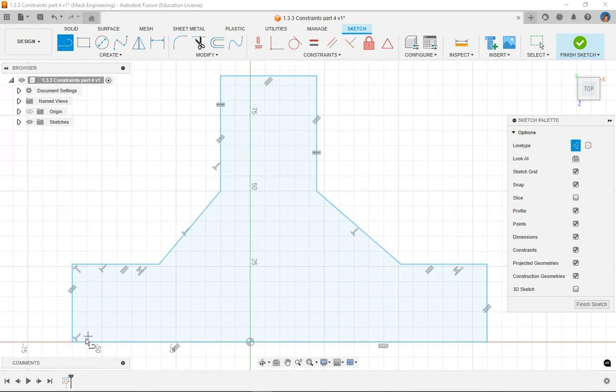Now we're going to go down to line 1 on our x-axis, and we're going to drag our cursor along. You'll notice it's just showing x's and squares as we drag along. Once we find the midpoint, those x's and squares will change to an X and a triangle. So once you find that, you want to click. That will place that first point right there on our line 1.